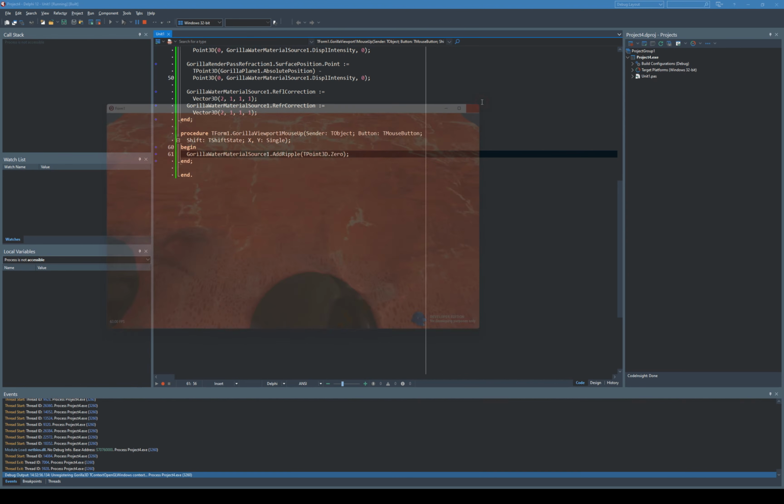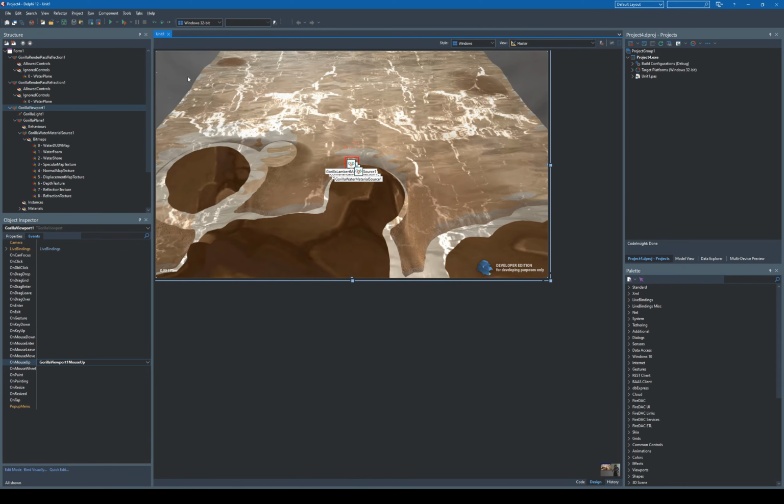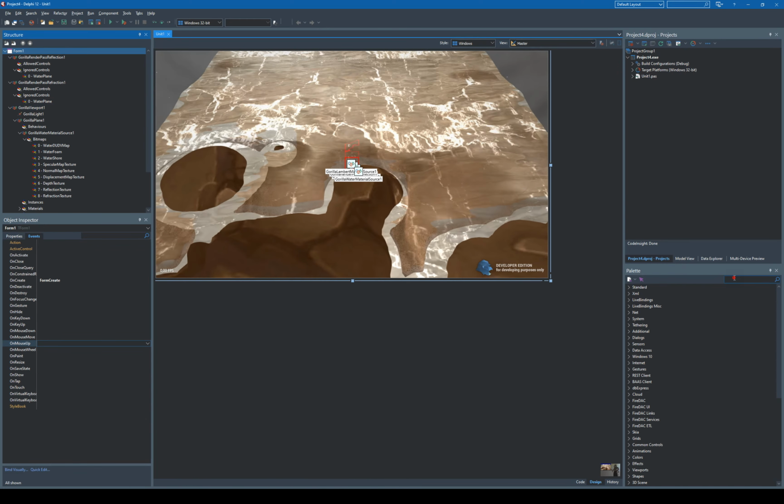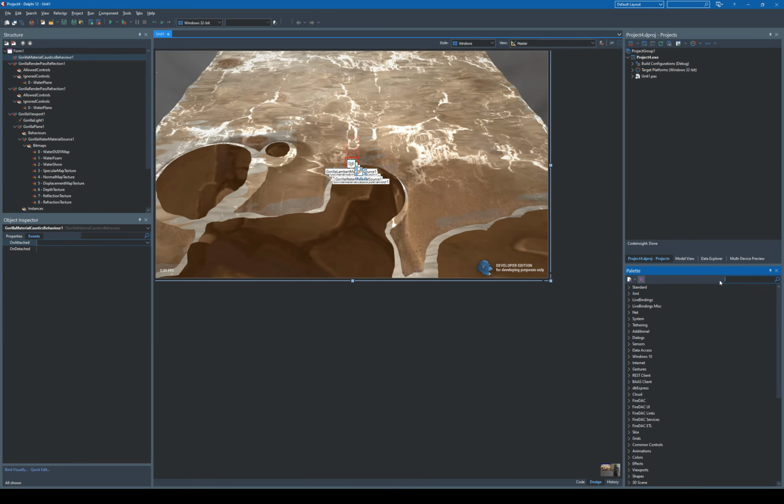Further optimization to our scene is water caustics on underwater sections. Caustics are reflections on a surface produced by the light falling through the water surface and then hitting a ground. Computing this light behavior might get too intense and would need ray tracing techniques, but there is a simple way to simulate the result. We provide a material behavior component for caustics, which can be attached to any default material.